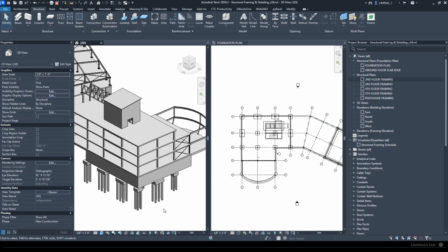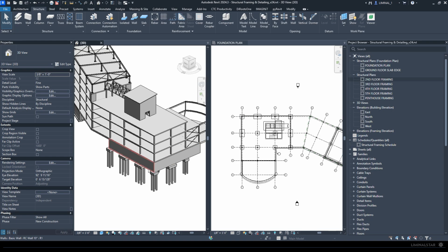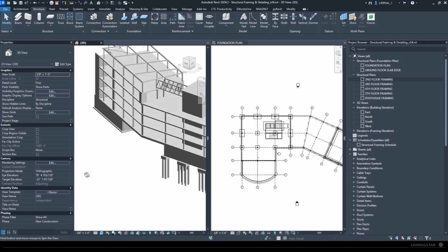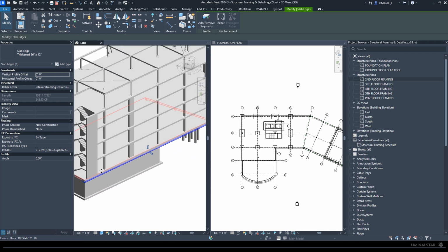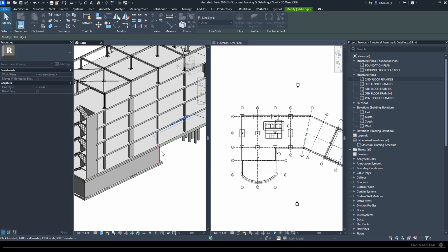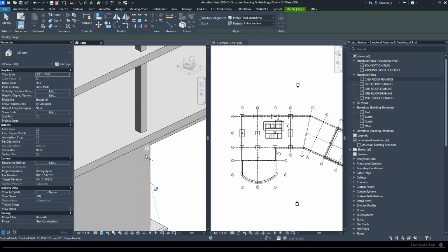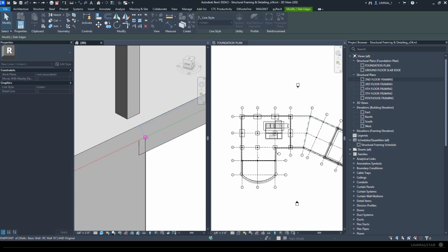If you're following along with the structural series, we took a little bit of a look last time on how to create some of these foundations that we're seeing here. So we've got some piles and caps, we've got some foundation walls, I've replaced the grade beams that we had in there from before. We've got a couple floor sweeps here, or slab edges I guess you want to call them. You want to make sure that those don't go all the way through. So there's easy ways to make those edits. That's just kind of pulling those nodes back.